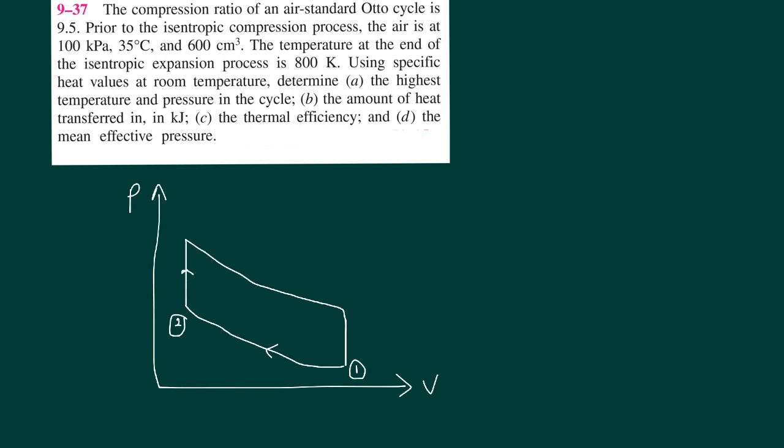And in the Otto cycle, your heat addition or your combustion process happens at constant volume, and then it goes to state 3 where the complete combustion process is happening, and then your piston cylinder are going to expand, and finally it will reject your product of combustion as an exhaust gas. So we define this for one state as Q out, right?